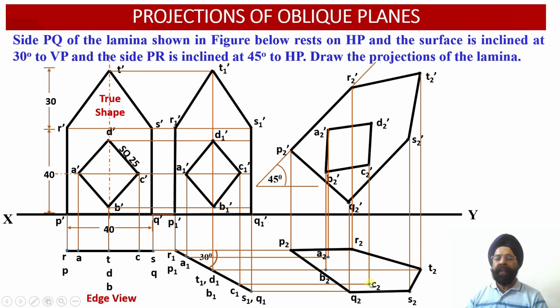we have obtained the point C2 over here. And finally this is the point D2 dash corresponding to the front view projection. Now from D2 dash we have drawn a vertical projector line and extended it up to the limit where it is going to intersect with the horizontal projector line emerging from the point D1 over here. So the intersection of this projection line through D1 and this vertical projector line through D2 dash will provide us with the location of the point D2 corresponding to the square hole. Now we can check once we join A2, B2, C2 and D2.